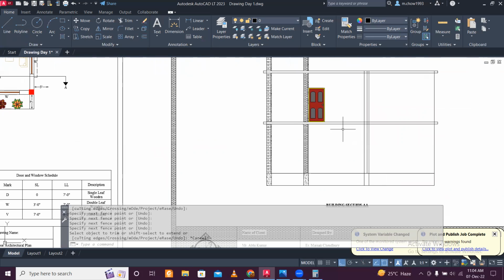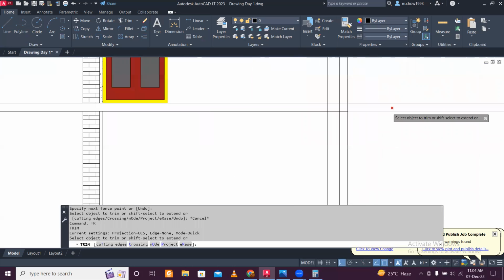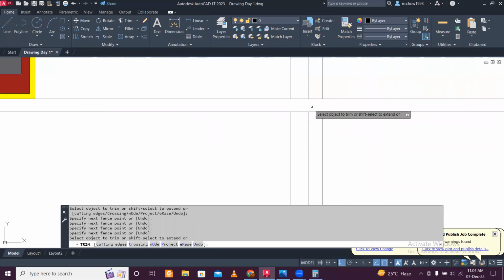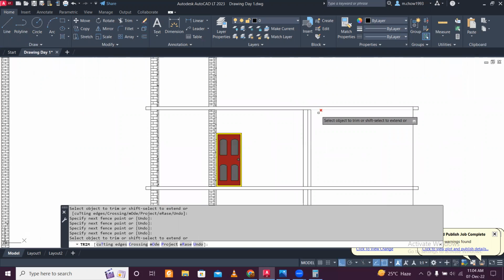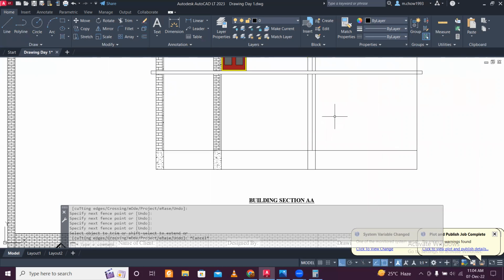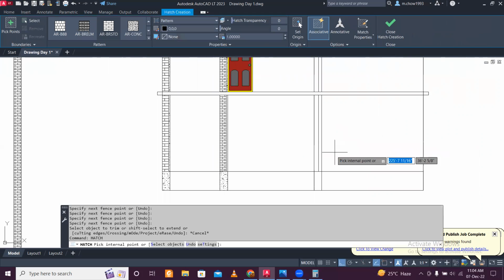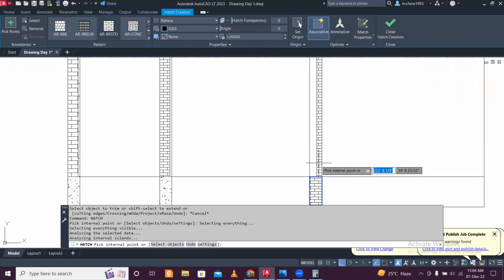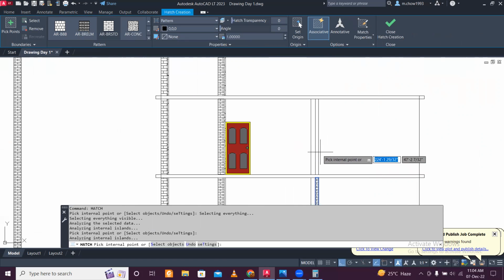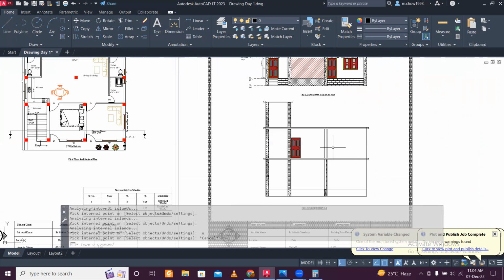RCC visible. Okay, so this is the case, and obviously trim the portions which we don't need in the slab. Okay, so the slab portion is trimmed, and now you can just go and do your hatching. As I said, remember, don't underestimate the hatching. Hatching is very important, and it is conventions. If you get your drawing checked, many people take that seriously.